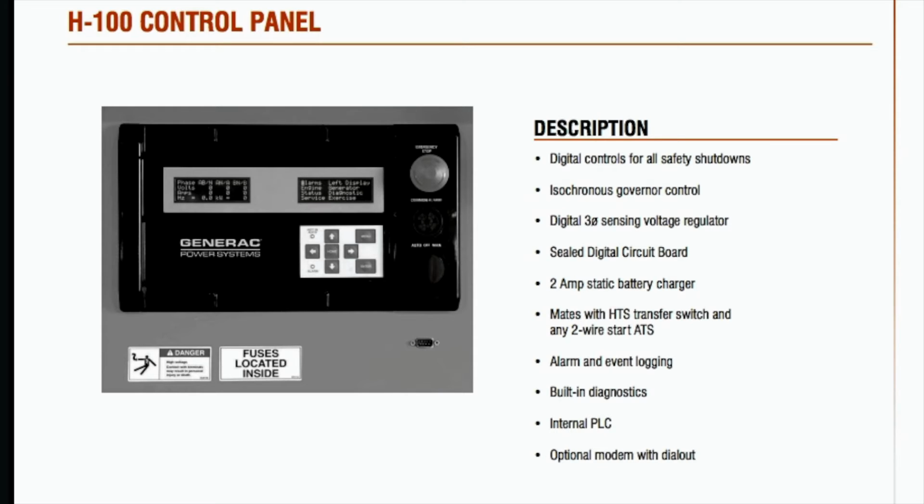The H100 control panel controller is set up in the factory to match the product it is shipped with, and generally no changes are required. For spares purposes, the controller can be reconfigured in the field using the GenLink software tool and a PC. If you need to change the function of the panel, the best way to get a basic setup for a product is to use GenLink to download a product file. This will set up all the basic parameters and just leave customization and calibration to be done. Product files are available on the website for downloading, cross-referenced to product serial numbers and generic product types.